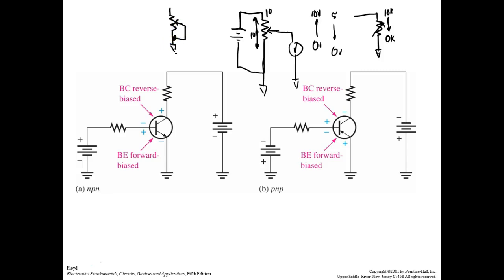And so you're going to run into a lot of pots wired as a rheostat, because here's something that can serve two functions. They cost about the same price per K, so you can't hardly find rheostats anymore. Because why? Because a pot can do the same thing if you wire it correctly. If I wire a pot like that, it acts like a rheostat. If I wire it like this, it acts like a potentiometer. So I've got to be real careful, because I could create a short circuit with a rheostat.